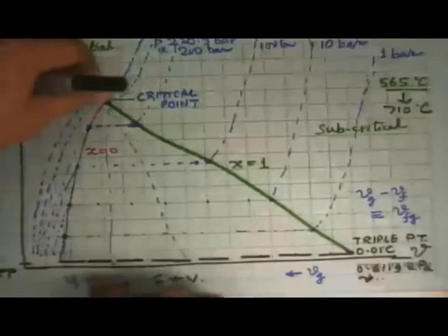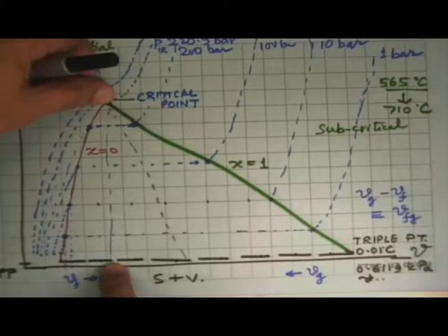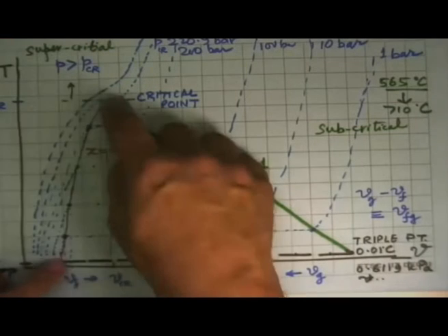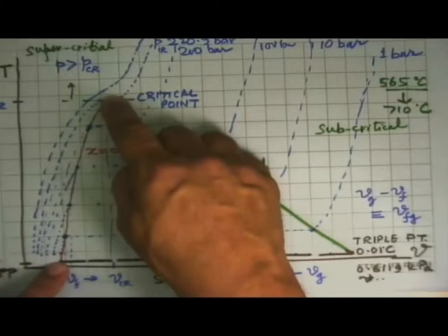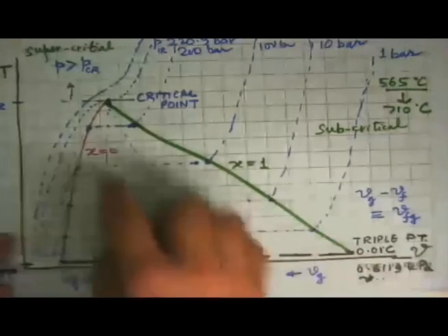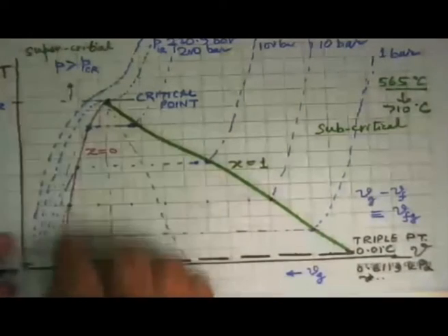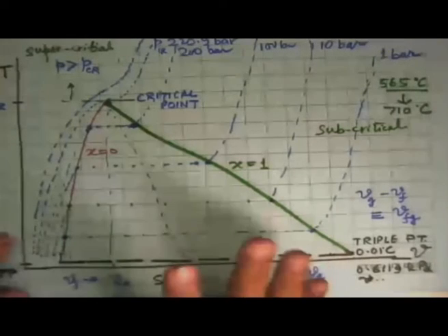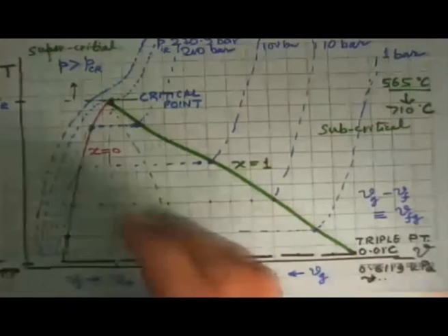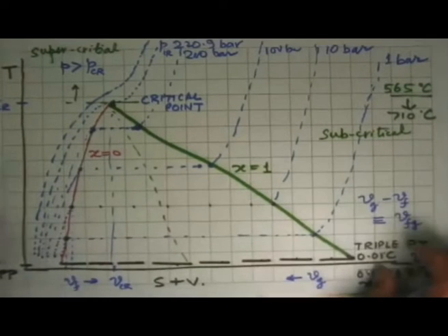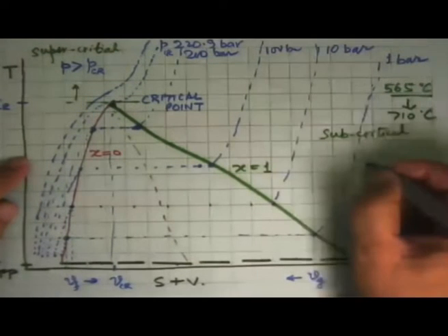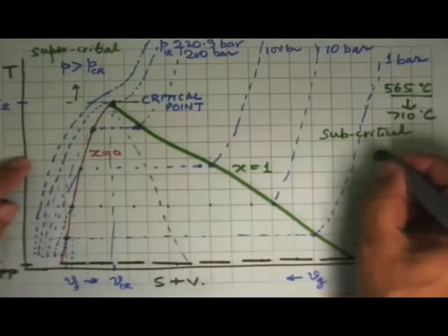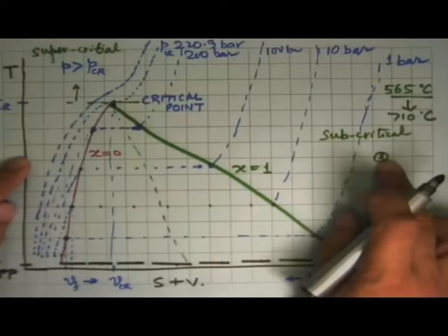If temperatures are between these two values and pressures are between the corresponding triple point and critical point pressures, only under those conditions can we expect to see a wet saturated state. It is not necessary that it will always be there, because at this temperature, if we have this pressure, it is a superheated state.